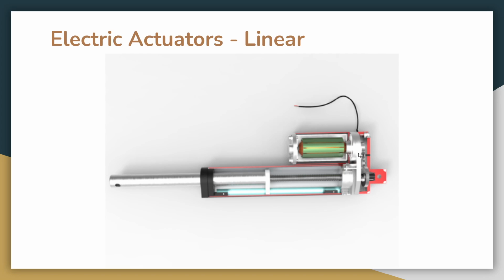The motor rotates and then this gear rotates, and because this gear is connected to this gear, it also rotates, and there's a screw structure, which, if you guys have all used screws, right? So once the screwing mechanism happens over here, the whole piston-like structure is pushed forward. There's a translatory motion occurring because of the screwing motion.